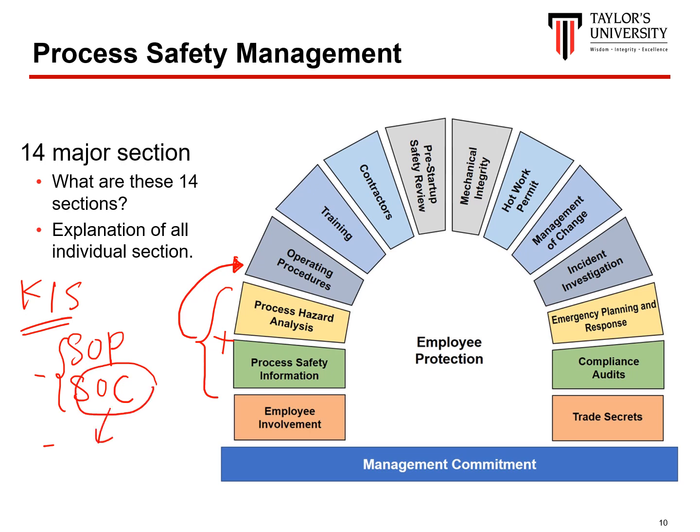For example, the vessel is supposed to run at 400 degrees Celsius, but now it is running at 600 degrees Celsius. What do you want the operator to do? Okay, and also we have to specify the hazardous properties of the chemical, the exposure precautions, the engineering and administrative control, etc. Safe work practice has to be documented, such as hot work, lockout, tagout, and confined spaces.